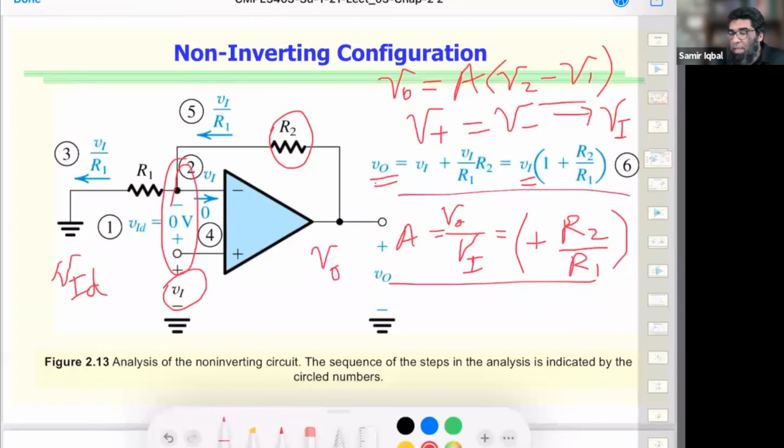Which is the basic behavior of an op-amp. But a fraction of this increase goes back through R1 and R2 to the inverting input. And this will then counteract the differential voltage. The feedback will bring it down to 0.